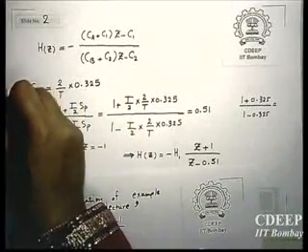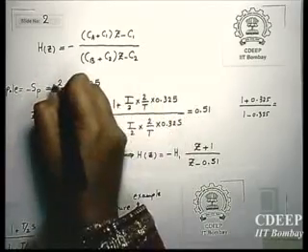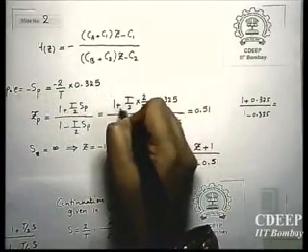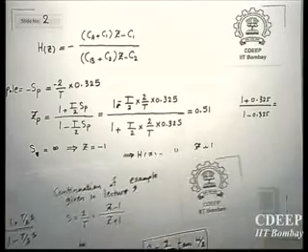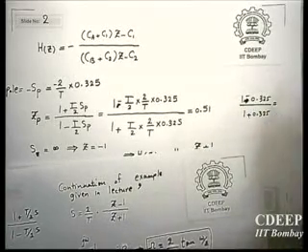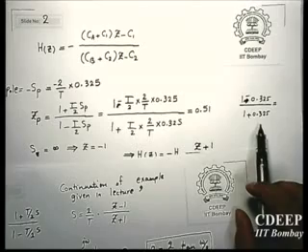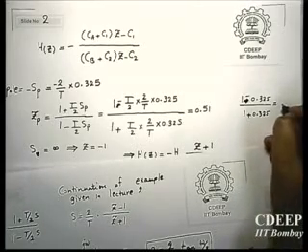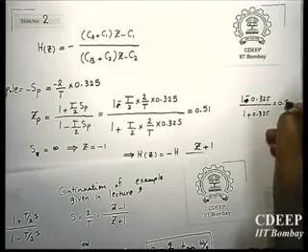So the pole is equal to minus SP, therefore this will be minus. Now this becomes minus, this is plus, so this will be around 0.7 divided by 1.3, which is around 0.5. It's not exactly 0.7, 0.6 something, so it is around 0.5.